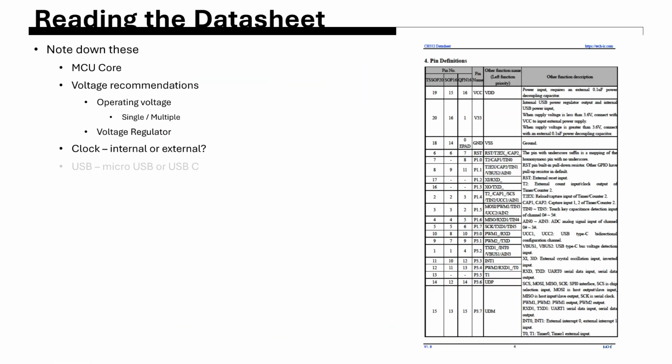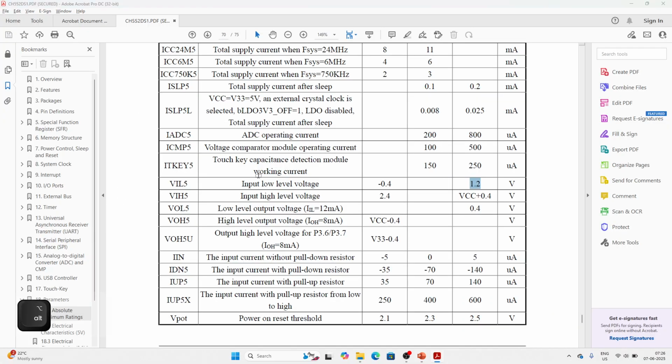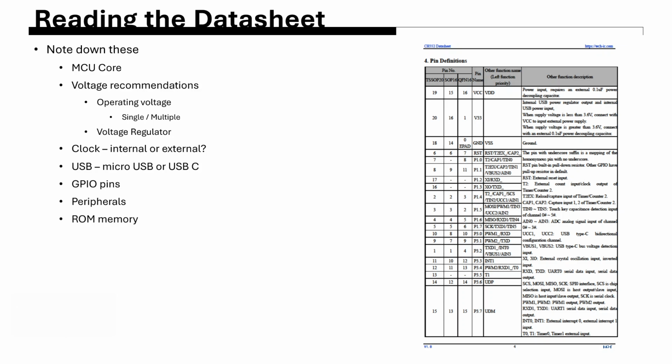After that, we will look into peripherals. As we saw, it has multiple peripherals, UART, touch. I did not see I2C on the datasheet, but I2C can be implemented in software by bit banging, right? But it has SPI communication and various other ways.